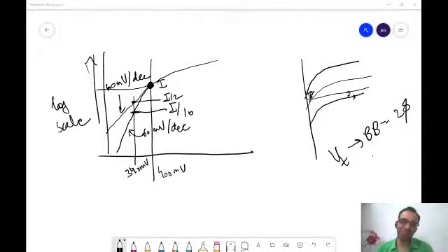So the standards simply keep on confusing you, right Ranjit? Yes, sir, just with the units. So the standard definition is 1 ampere, or 1 microampere, per micron length. So whatever it is, per micron width, it's a constant current. That is the definition. That is the thing that you need to take back.